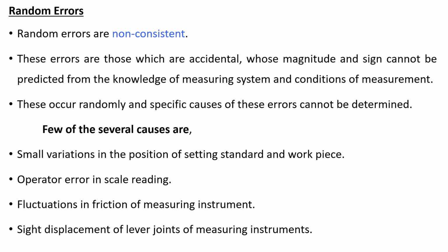A few of the several causes of random errors are small variations in the position of setting, standard and workpiece, operator's error in scale reading, fluctuations in friction of the measuring instrument, and slight displacement of lever joints of measuring instruments. These are a few causes of random errors.